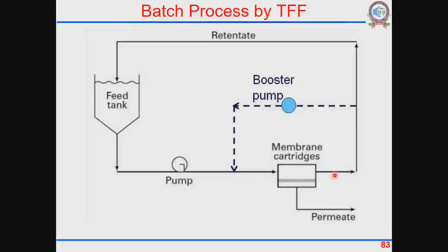Just to look at different applications, different processes, let's imagine a batch process. So here is where we will feed our solution to be concentrated. Let's say we will pump it through a module. Now each of these modules could be a plate and frame module or a spiral module or a hollow fiber module. We will get permeate from one side, so it is only a schematic representation,